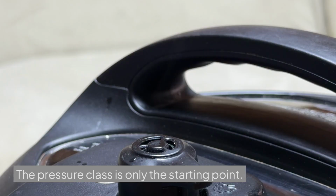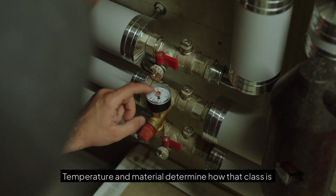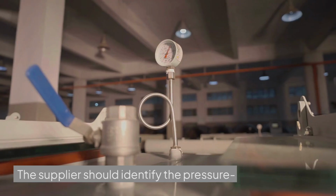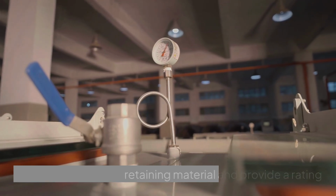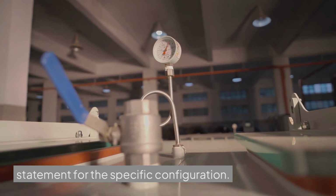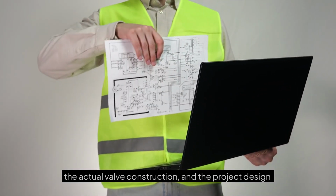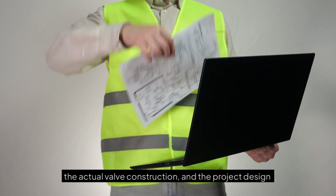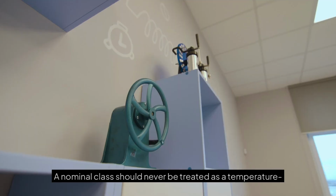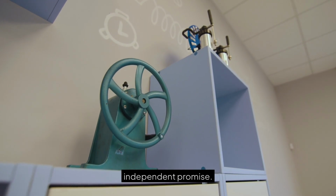The pressure class is only the starting point. Temperature and material determine how that class is applied. The supplier should identify the pressure-retaining material and provide a rating statement for the specific configuration. This creates an auditable link between the selected class, the actual valve construction, and the project design conditions. A nominal class should never be treated as a temperature-independent promise.